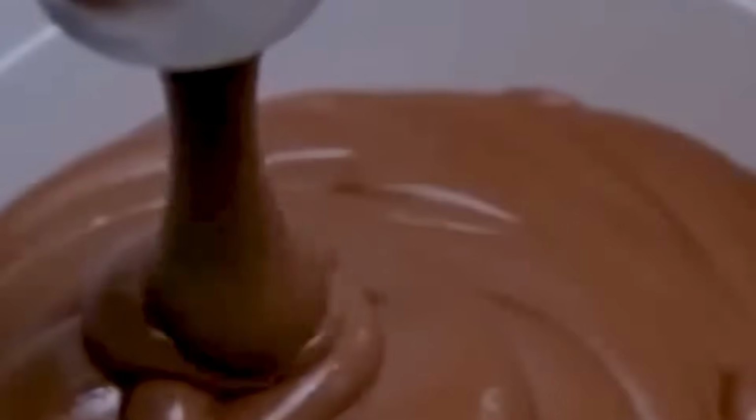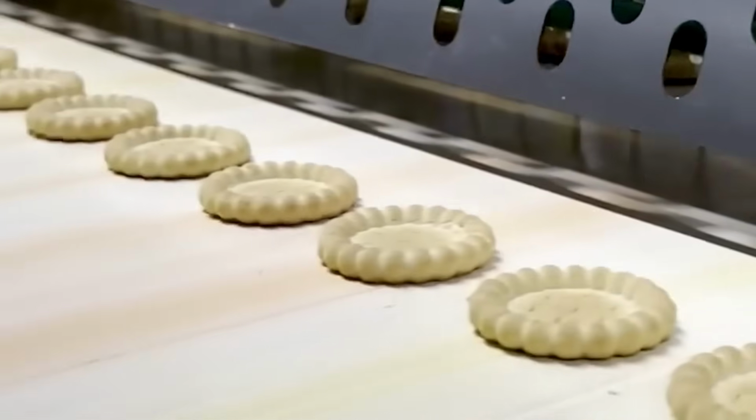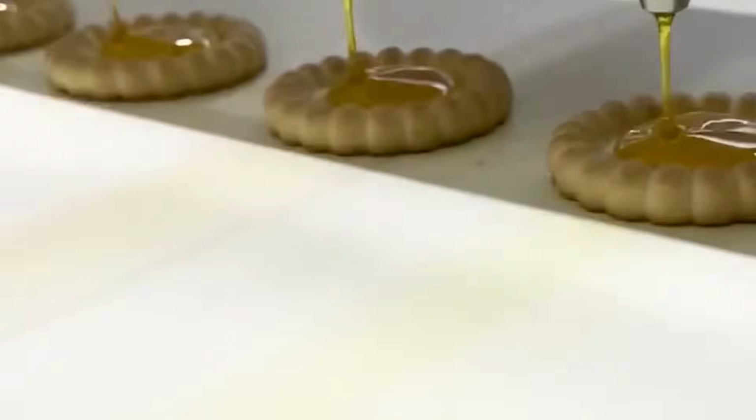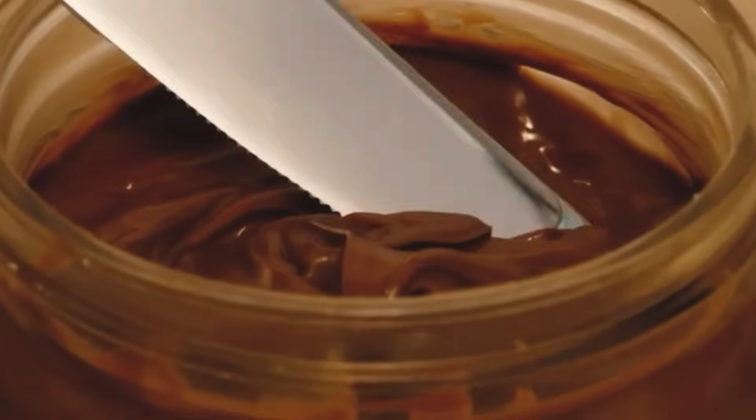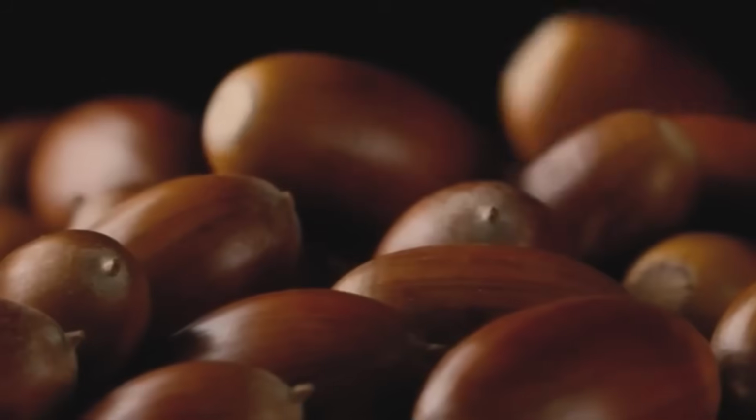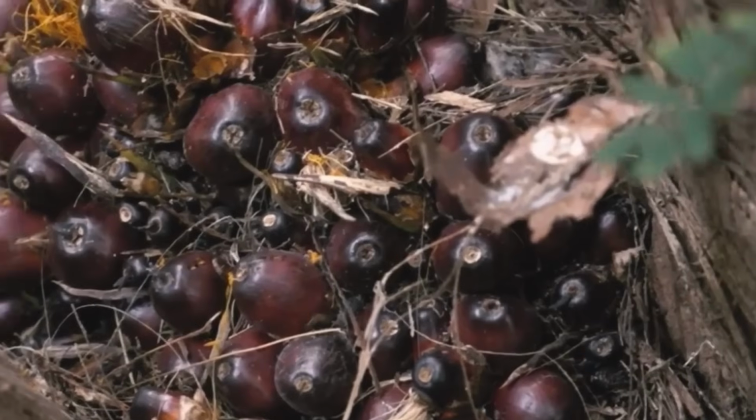Cartons are weighed for content verification and stacked into larger corrugated shipping boxes using layer-forming robotic packers. Palletizing is performed by 6-axis robotic arms with end effectors designed to grip multiple boxes per cycle. Standard Euro or industrial pallets are loaded based on customer logistics requirements. Pallet patterns are configured to ensure structural stability and airflow clearance.